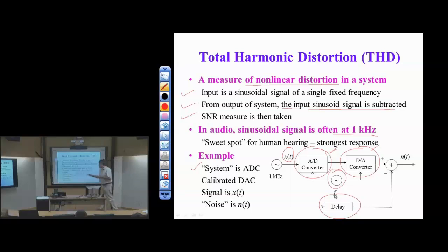All right, fine. I can also even do it for this particular test signal. I can separately calibrate for that frequency, figure out what's the delay that I see on the output. Correlation. All right, fine. So I got a delay. It's a fixed value. And now the difference is the noise. This is all the other stuff. This is additive noise in the system. This is nonlinear distortion of the 1 kilohertz sine wave. This is everything else.